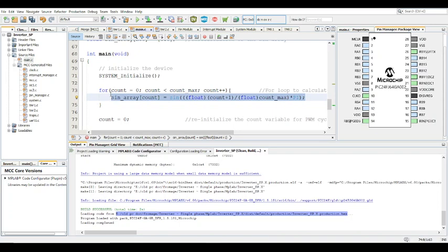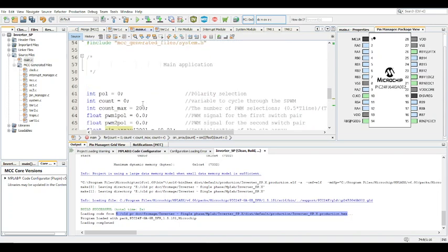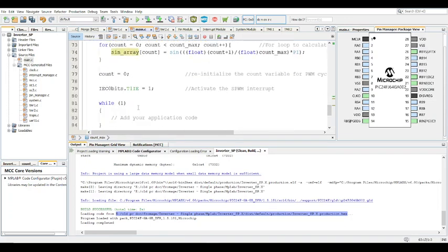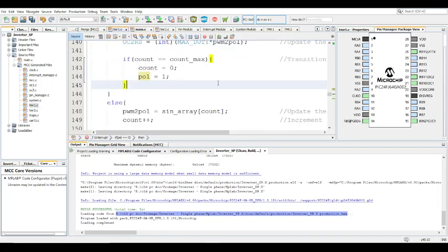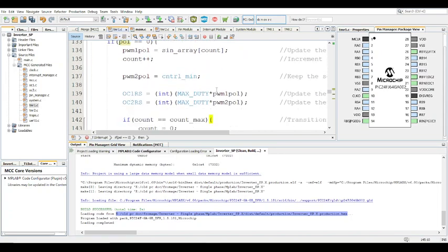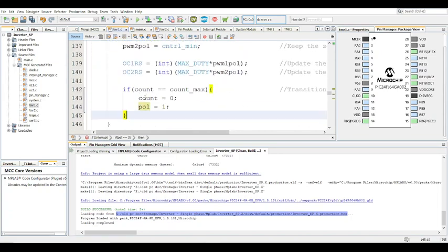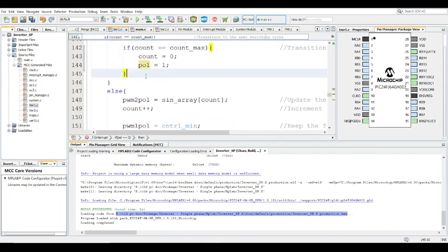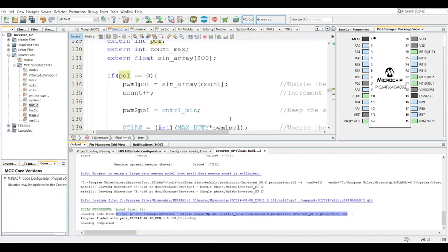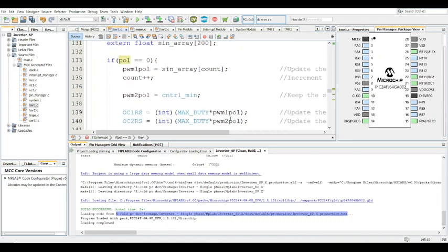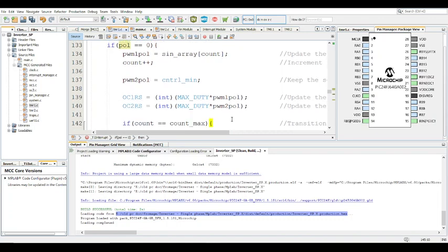And this is the main function to use to calculate everything, all the duty cycle changes, the SPWM, right? The PWM values for each position, for position 1, 2, 3, all the way up to 200, up to this value here, which is the maximum count, right? And then you activate the timer, and then in the timer it switches sides, right? So polarity 1, polarity 0, sorry, and then polarity 1, and that's essentially it. That's how it's done. You just take it from there.